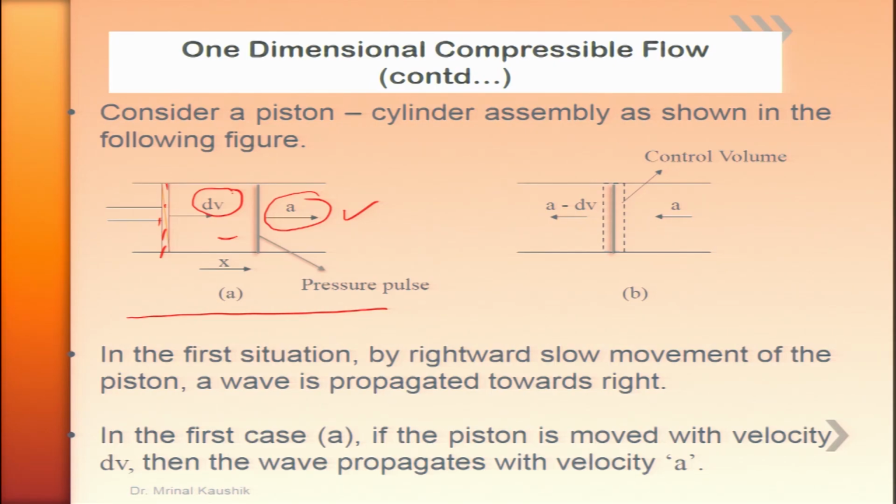That means I myself go and sit on this wave. If I am on this wave and start observing the flow phenomena, because what I am interested in, rather than a moving wave front, for simplified analysis, is a stationary wave, and across that stationary wave, let the fluid flow. This condition, as soon as it is reversed, is shown in B.